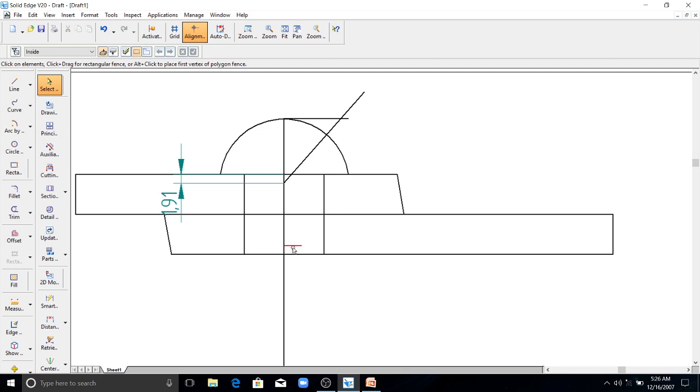You will get this center by the similar procedure I used here, by allowing this height, leaving 0.8 d and bisecting this line. So you will get this same point. Instead of doing this lengthier procedure, just copy this dimension from here to here. Since both dimensions remain the same, the same center will come here. So you can copy this distance and leave it here.